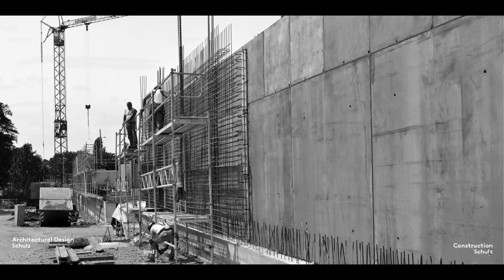When positioning dimensions, it can be helpful to imagine where the builder would be in relation to the component. Ideally, you should position the dimension exactly where they would be standing. Here, you can see concrete workers at work on a building site. The plan is spread out on the scaffolding immediately in front of the point at which they are working.